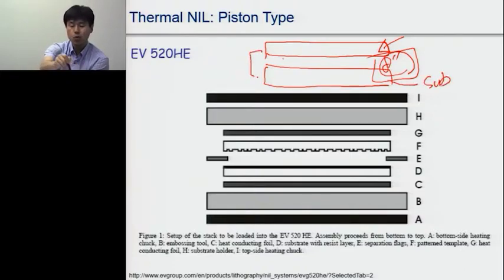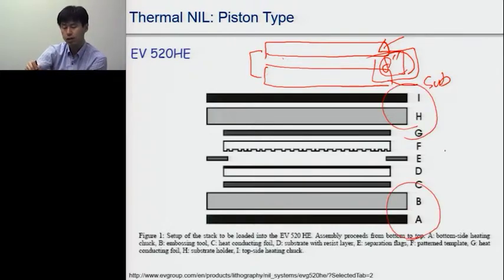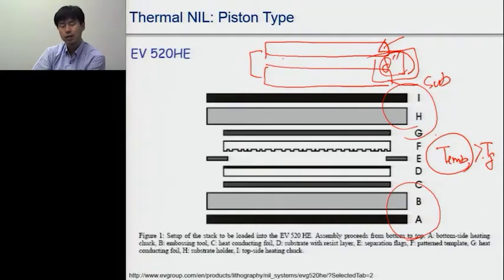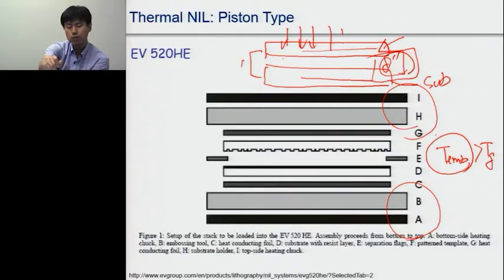Say our master mold is an 8-inch wafer and the substrate is also an 8-inch wafer. At some point, when the upper stack and the lower stack reach the embossing temperature, which is higher than the glass transition temperature, we need to apply pressure. Since the radius of the substrate and master mold is pretty big, if we suddenly apply the pressure, some of the air cannot escape properly.